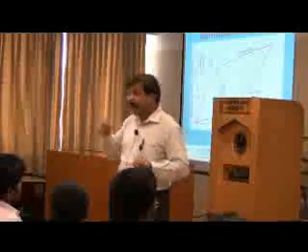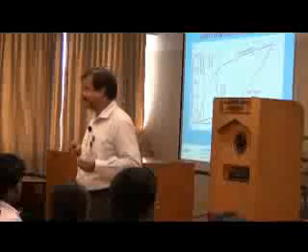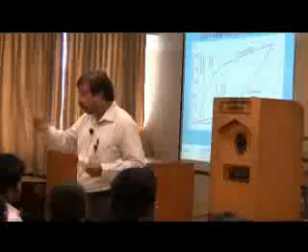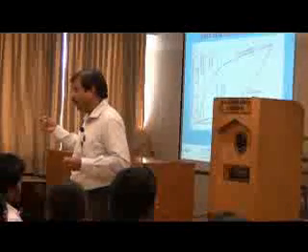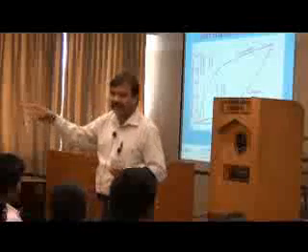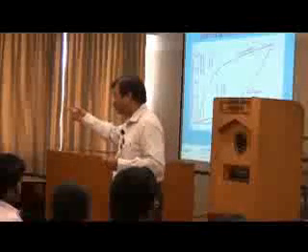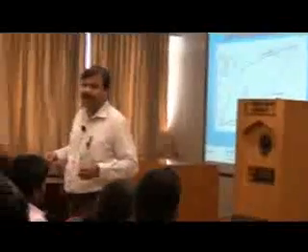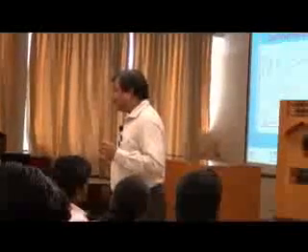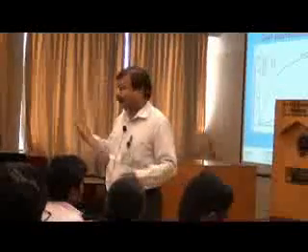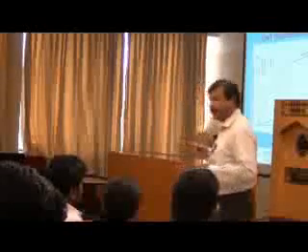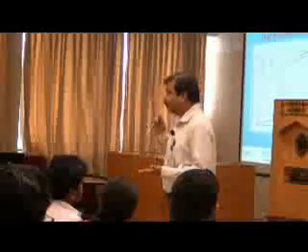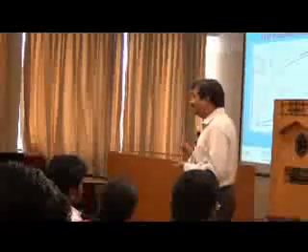During the design phase, I am supposed to take a decision regarding this. I should specify what material I should use for making this particular component. When I say it is stainless steel, the cost is going to be 10 times more. The cost of low carbon steel, for your information, in today's market is around 40 rupees per kg. On the other hand, the cost of stainless steel is around 340 or 360 rupees per kg. So when I make a decision about the material choice, I do make a commitment.